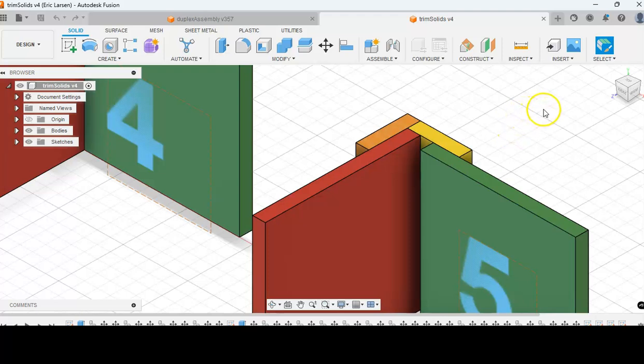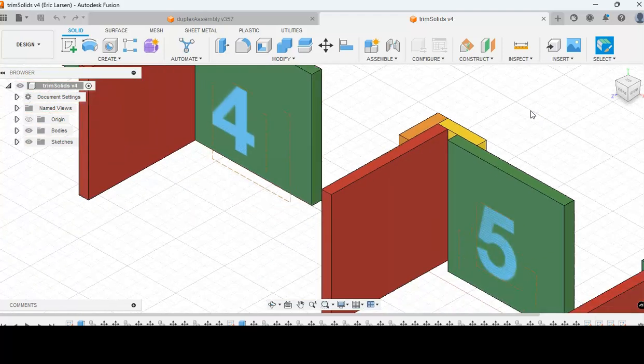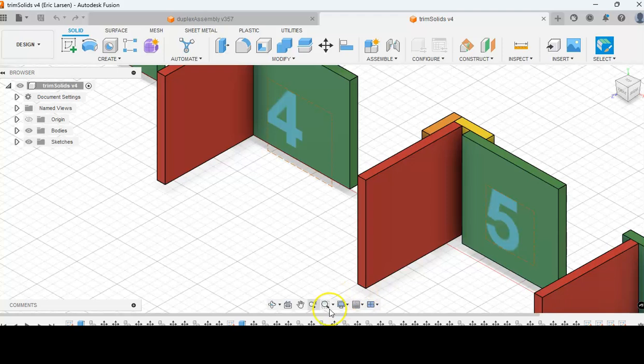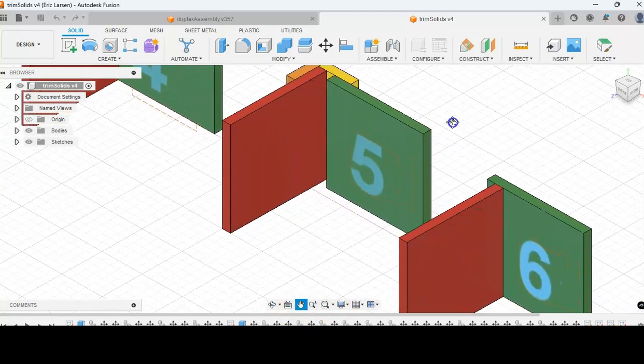But if you've got more than about 1/8, you may need to do something about it. What you can do is simply cut a piece of sheet material that will slip in here, and that will work. But you need to consult with your site carpenters and your experts.